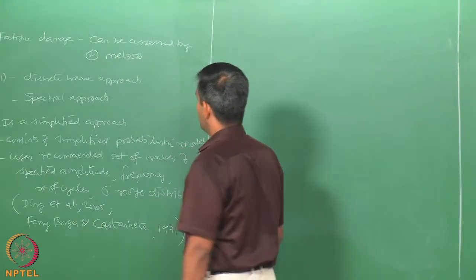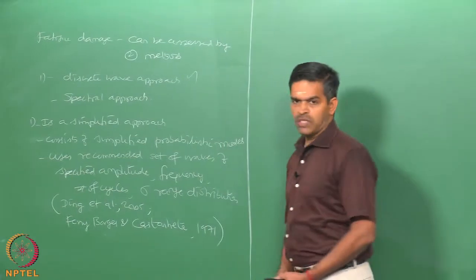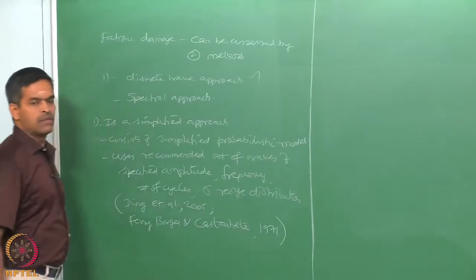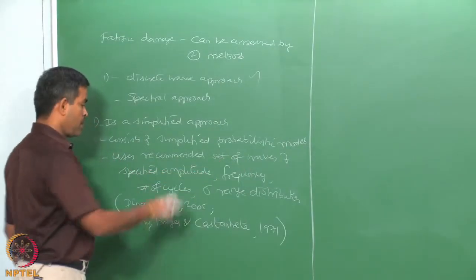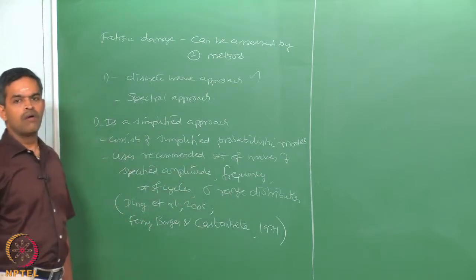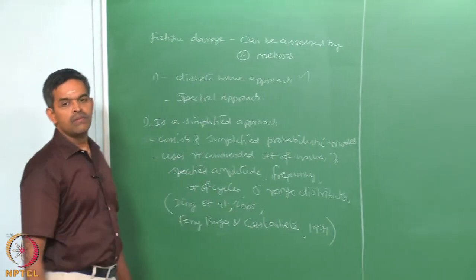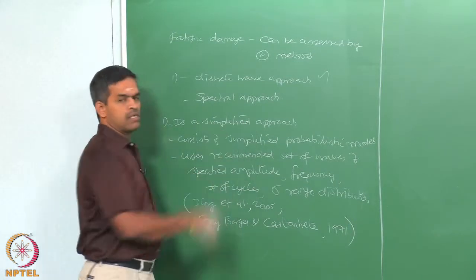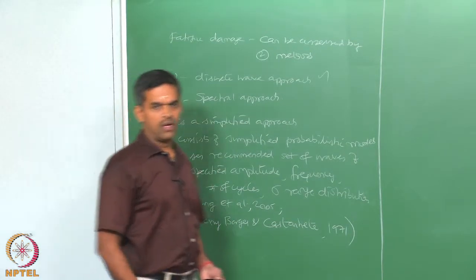So, discrete wave approach uses specific amplitude of waves, the frequency content, the number of cycles or the stress range distribution for estimating the fatigue failure, which is more or less a simplified approach suggested by the researchers.